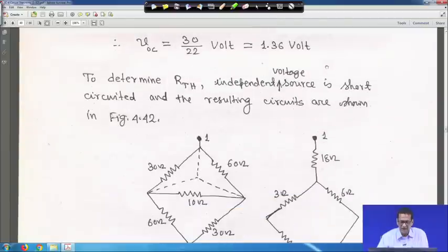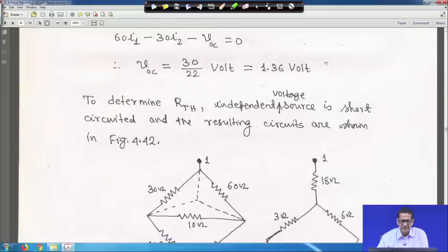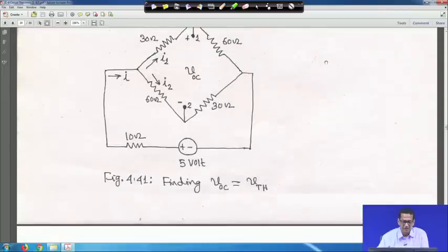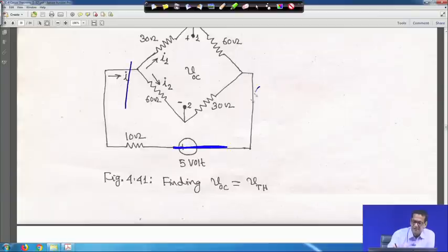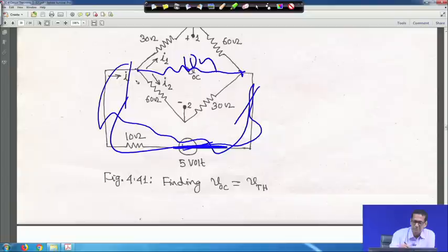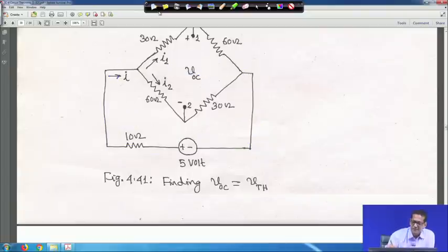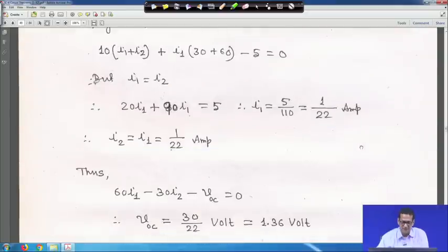your equivalent R Thevenin. So, what you do is this will be shorted, look at that, this will be shorted. That means this 10 ohm resistance, suppose it is not there. So, this will come here, because these 2 points are connected, nothing will be there. Suppose I am making it for you, suppose it is not there. So, 10 ohm will be here, right. So, let me clear it. So, that is what we have done here, right.